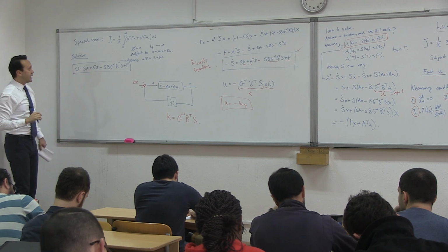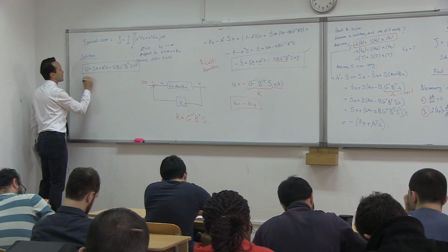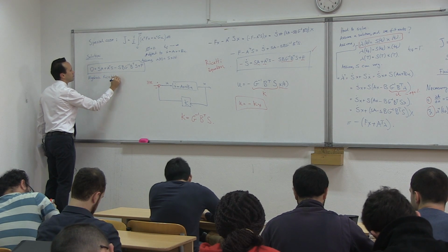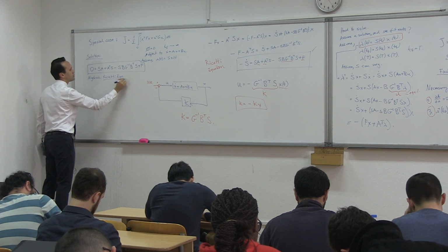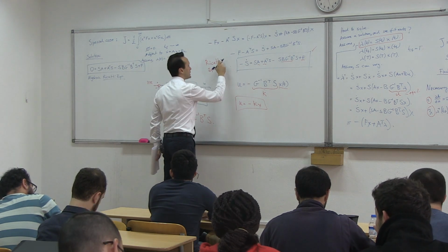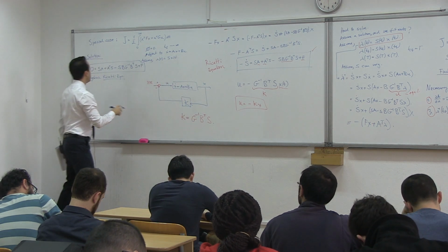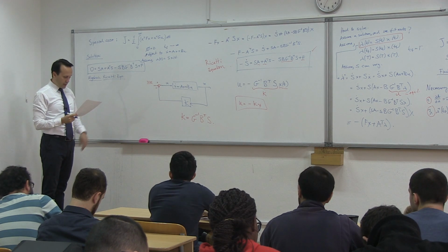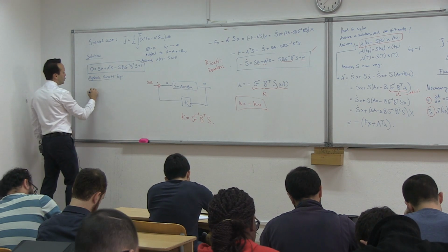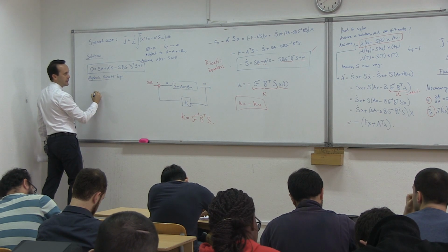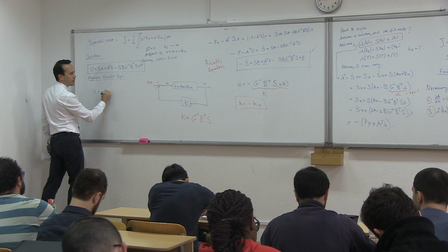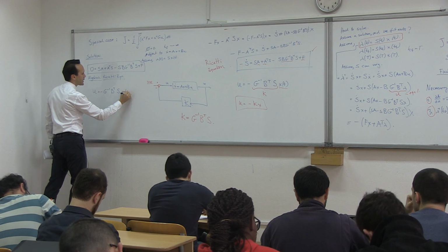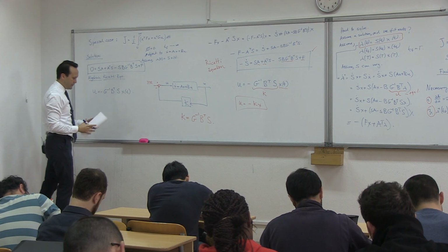And this is, again, called the algebraic Riccati equation. And the way you see it, there's no s dot, so it is not a differential equation. It is an algebraic Riccati equation. So it's an algebraic equation that we can solve. And the controller, u, will still be the same. U is equal to minus g inverse B transpose S times x of t. Okay?